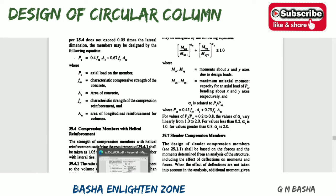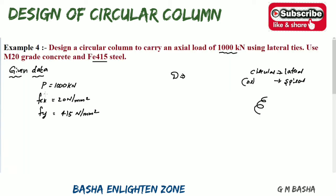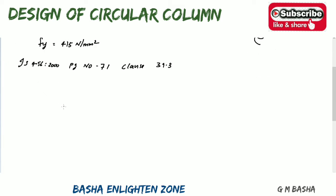That is clause 39.3 in IS 456:2000, page number 71. I am clearly mentioning that. So by using this formula we have to design the problem. What is the formula? That is Pu equal to 0.4 fck Ac plus 0.67 fy Asc.